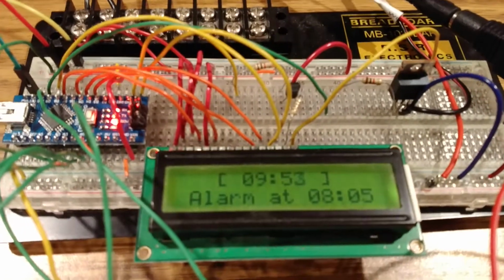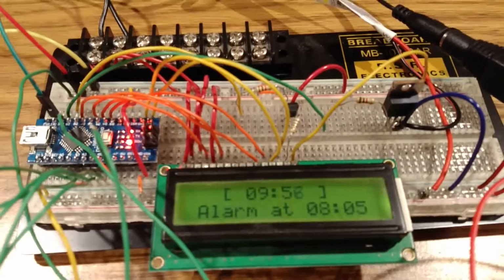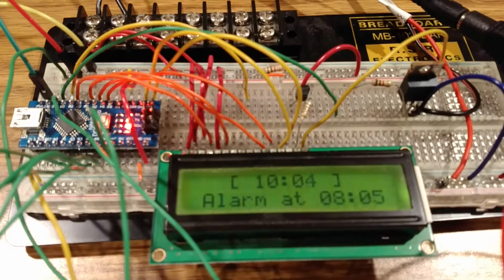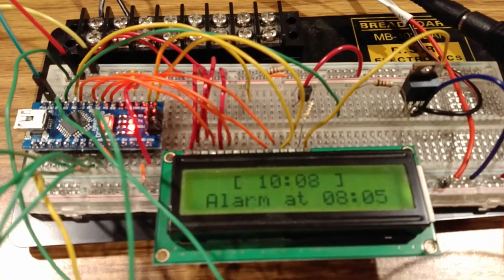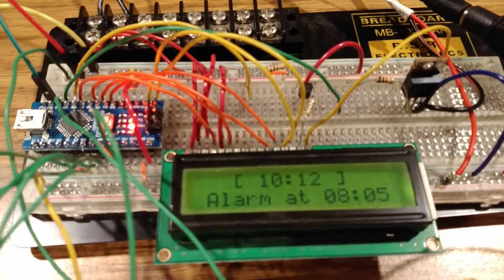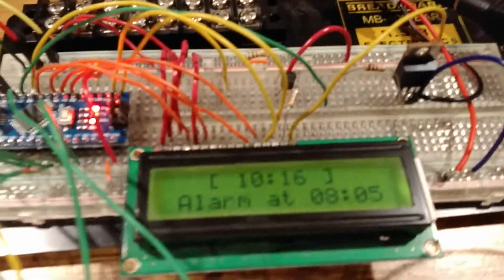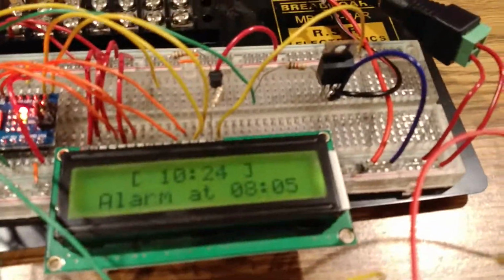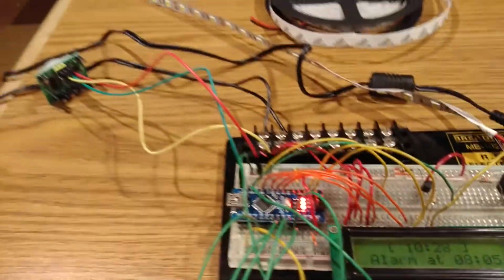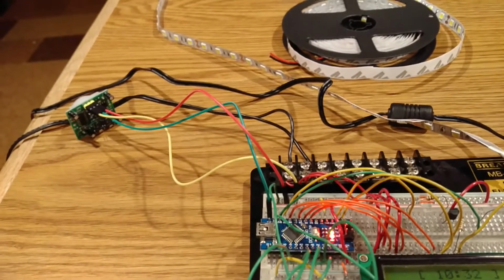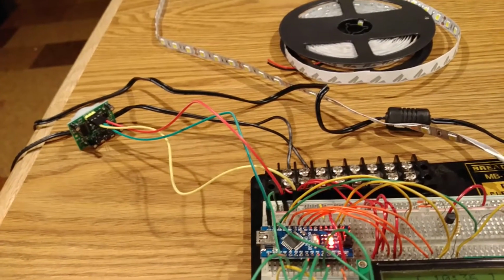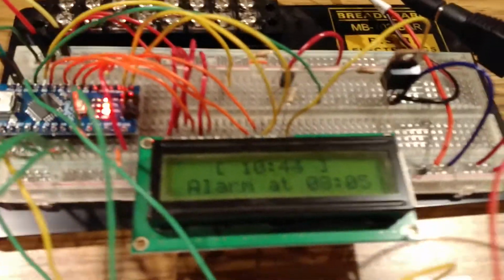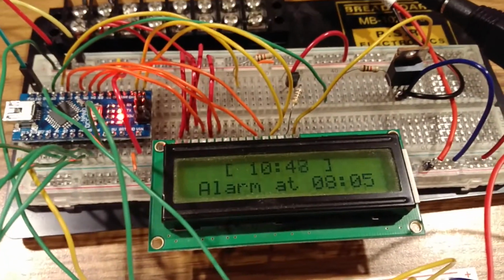The other feature I have is called night light or auto light. Even if you have that disabled, the LCD will still turn on, just so that the user in the middle of the night may be able to see the LCD if they want to see what time it is, or just to make it easier to see it even during the daylight. This will stay on for about 30 seconds, and that's determined by the potentiometer setting over there on the proximity module. You can change the setting for how long after a trigger it'll stay on. I set it to about 30 seconds, and the LCD LED is already turned off here.